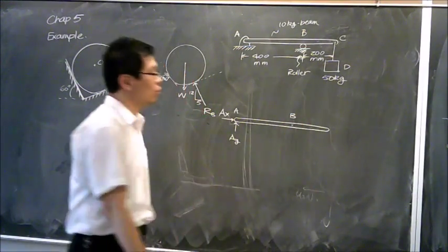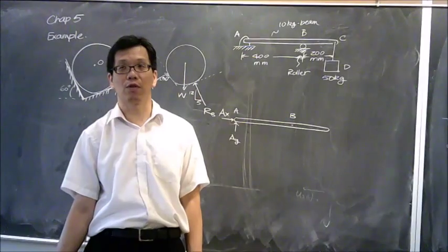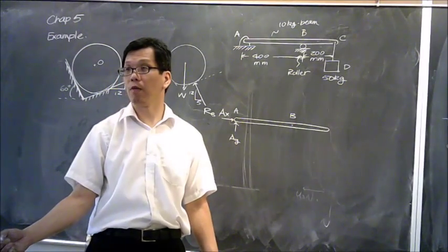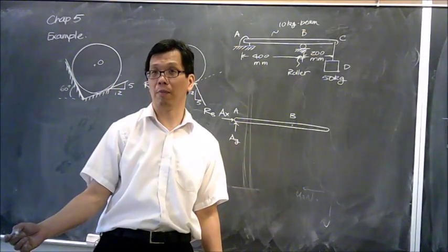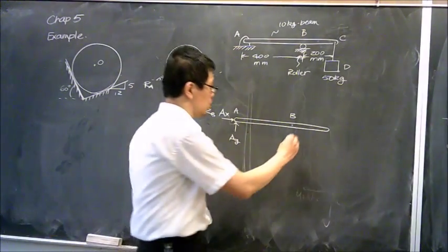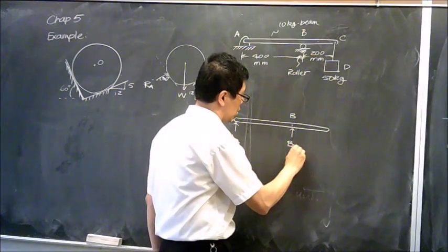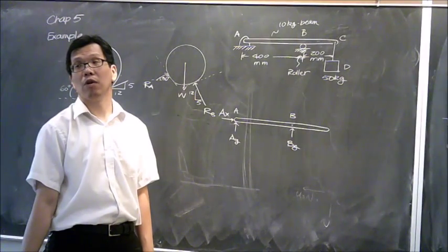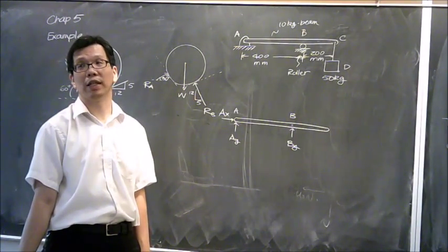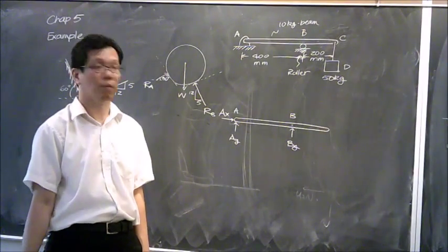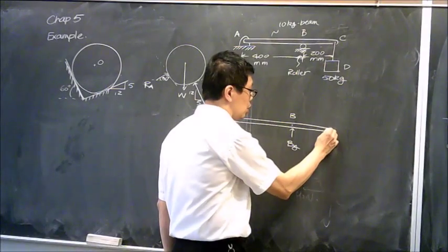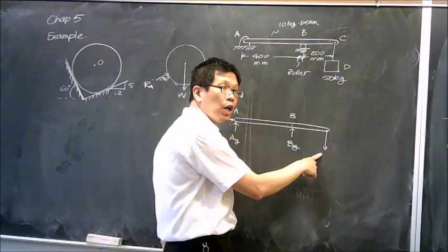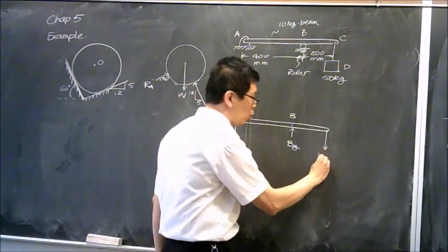What kind of forces do we need to deal with at point B? One force, two forces, or two forces with one moment. One force, what kind of force, which direction are we talking about? Upward. Okay, we have a connection at C, which is a cable. As a cable, what kind of force is it providing? Pulling or push? Pulling. So when we say it's pulling, is that downward or upward? Downward. Do we know the force over here? Why is that?